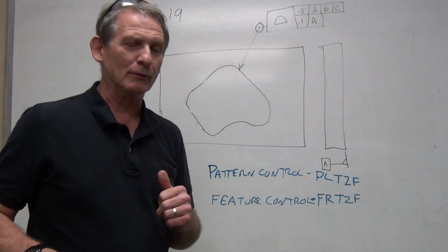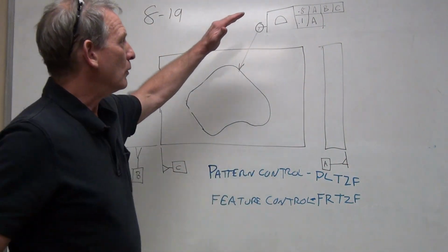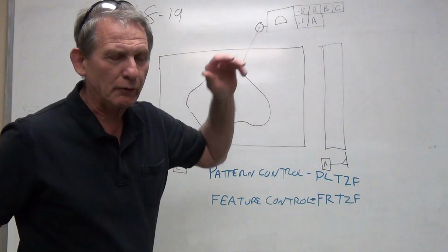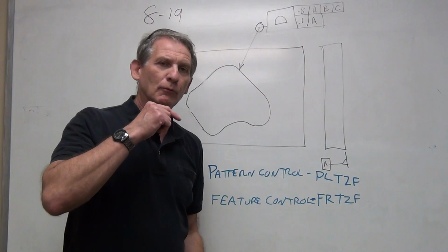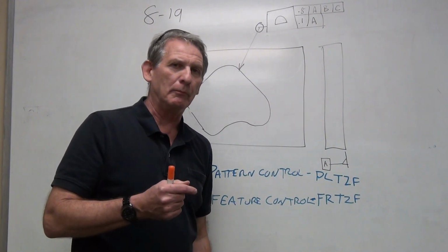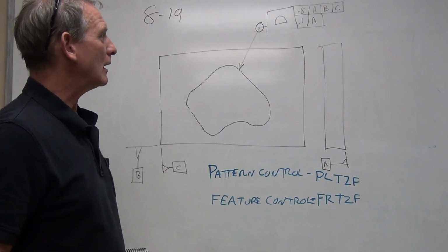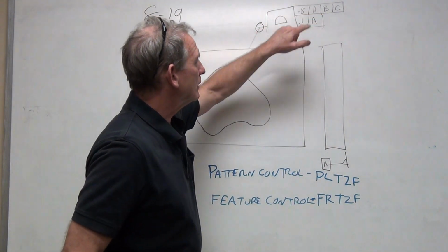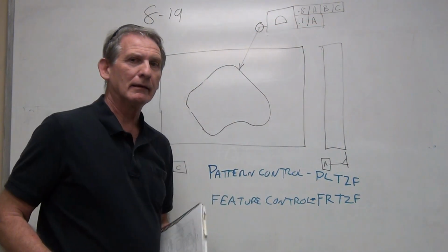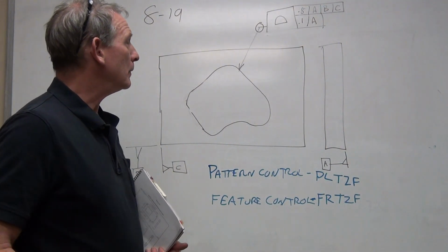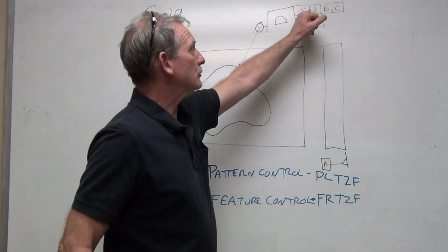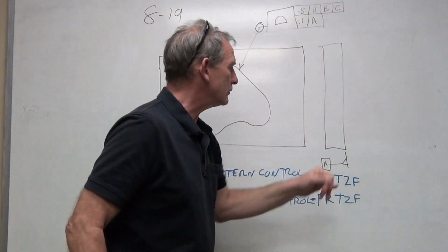How do you get 2 tolerance zones? Okay, so we'll go to the feature control frame. We see that we're dealing with a profile tolerance. In other words, whatever shape is there, we're going to draw a boundary around it. Now, what is that boundary? We're going to read from the top down. We'll see that there's a 0.8 millimeter tolerance, and it's referenced to datum A, B, and C.